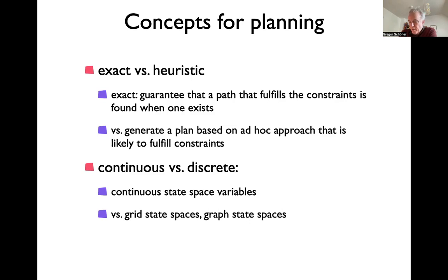And then there's also a difference between continuous state space planning, which is what we've done, of course, versus grid states or discrete state space planning. Sometimes discrete state spaces are simply discretizations of continuous spaces. For instance, reinforcement learning very often is based on that, where you have different cells in your state space, different positions or velocity values and so on. And you're really just planning how to go from one grid point to the next neighbor grid point. The discretization is useful because the algorithm for this form of planning, for instance, reinforcement learning, which some of you might know, requires discreteness.